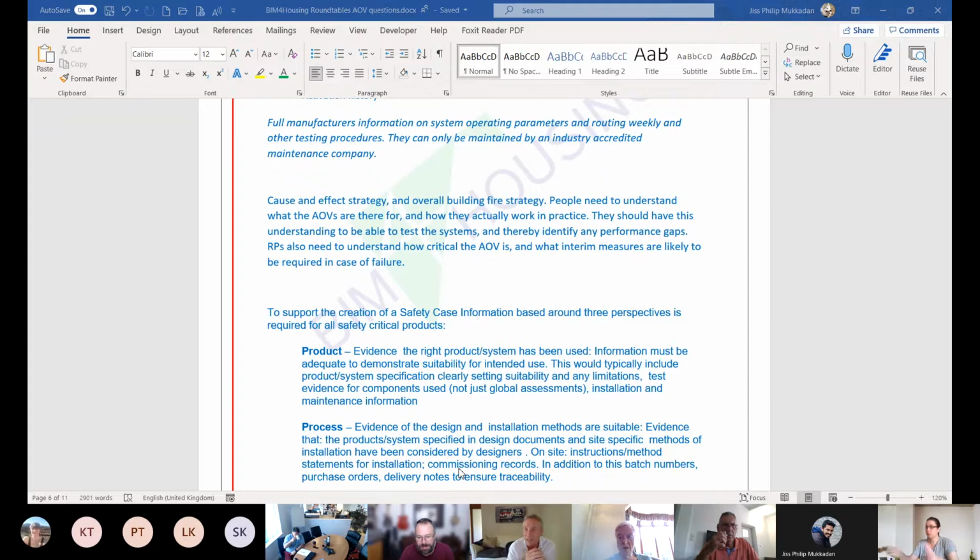Mm-hmm. Again, that's one of the tables I'd included, the smoke control extract from the Smoke Control Association guide, which tries to explain exactly that point you raised, Edward, because Approved Document B has got a 1.5 free area, which is just a hole in the wall, height by width. That isn't recognised by the 12101 Part 2 product standard. Therefore, that table says 1.5 is equivalent to 0.9 square meters of aerodynamic free area. That's what we tried to do as a trade organisation in that table I included.